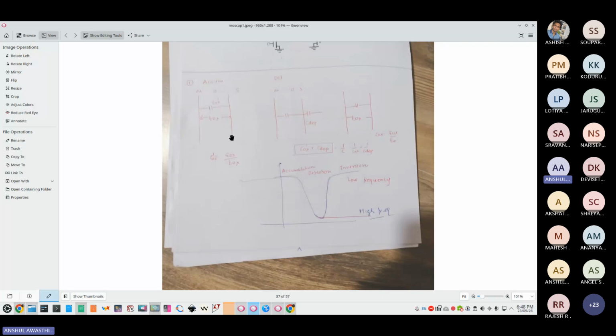First, initially, when the voltage is very low, hardly any change is there. Charges accumulate on the boundary, on the channel regions. Once the applied voltage increases, the second region will come, that is the depletion region. Charges start to deplete, and ions take the place of the charges. Wherever the charges were, it gets depleted, and that place has been taken by the depletion ions, that is, unmovable ions. They can't move.